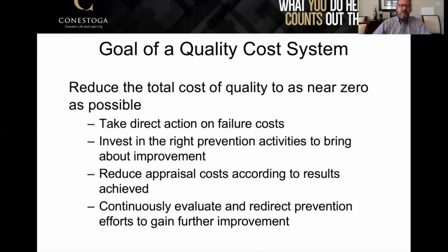One example in a manufacturing environment, very common particularly in just-in-time inventory systems, is that you'll push incoming inspection to your supplier. So when the tires show up at the gate for the shift that we're going to use to build that particular vehicle, instead of us inspecting the tires before we put them into the process, they're inspected by the manufacturer before they leave their facility. That pushes the cost down to them. It also means they're not shipping things that are defective, so I don't have to ship things back. It also means I don't have to have floor space in my facility to do incoming inspection. I also don't have to have people in my facility doing incoming inspection, right? You ensure they're doing those inspections based on an audit system with them, but you push that activity down to them. So there are creative ways that you can make sure the appraisal still gets done, but they're not necessarily things that you have to directly do yourself.